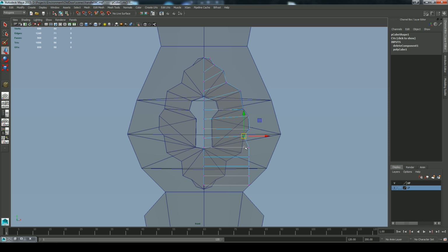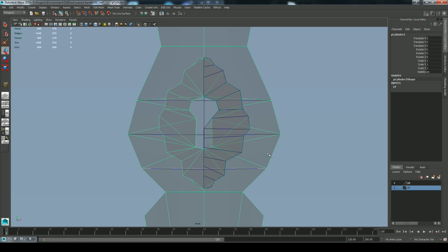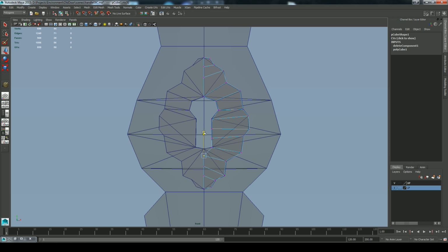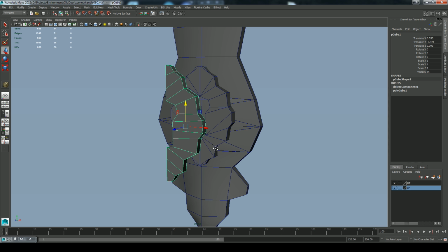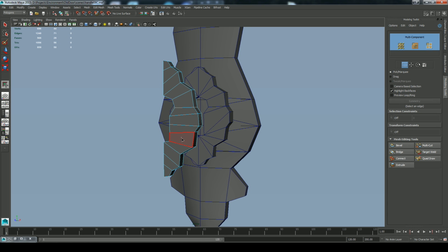Actually, a quicker way to do this would have been to turn on snap to vert, but this is working just fine. So as you can see, I've simply cleaned up that model just to make sure it's entirely in quads, but those edge loops kind of fan out around the lock shape. That's probably the quickest and easiest way to recreate that shape in quads, is simply rebuilding it like that. And you can see when I smooth it there, it collapses a little.